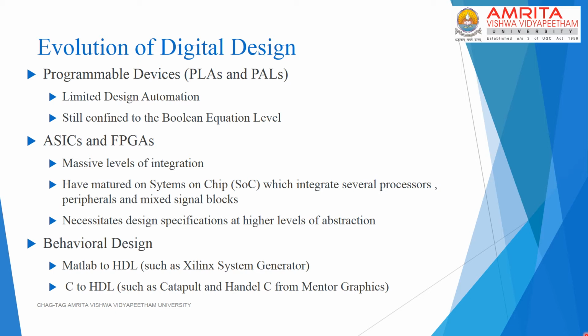And now we have reached a stage where there are tools available which can directly translate an algorithmic description in MATLAB or C into an equivalent HDL file, which can be eventually synthesized into a target library. So we have tools like the Xilinx System Generator and Catapult and Handel-C from Mentor Graphics, which are capable of translating or synthesizing high-level descriptions of algorithms to an equivalent HDL file.